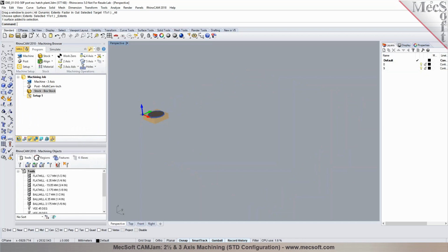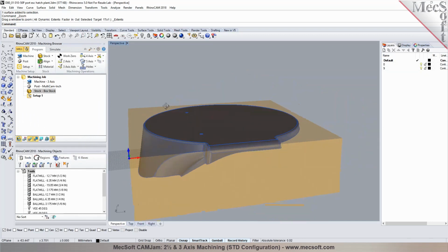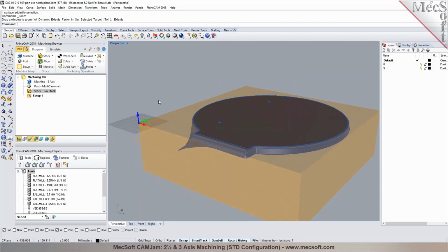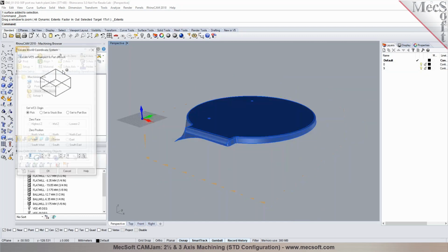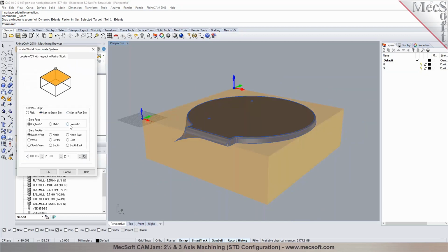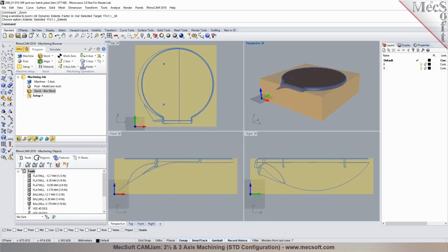Usually, because I've done some CNC with a different program, I've set the Z to the bottom of the stock. We could do that. It's just a preference on what you'd like to do. So we can do set to, we could do lowest Z, southwest. So what difference does that make when I'm cutting it? Basically, it means that it's going in the negative direction.